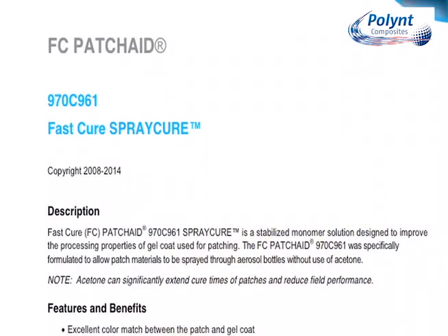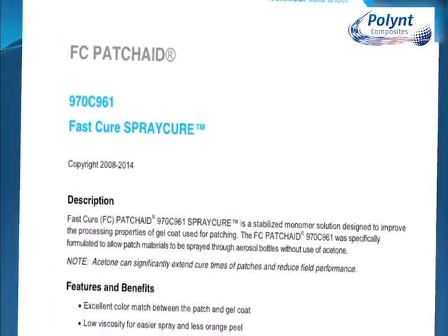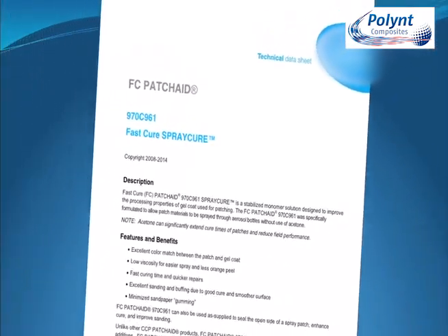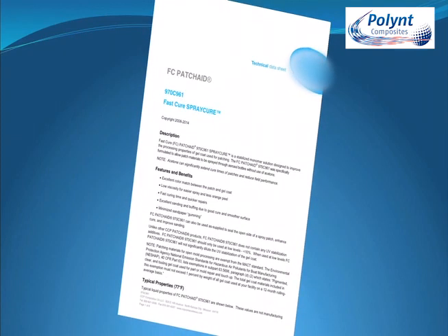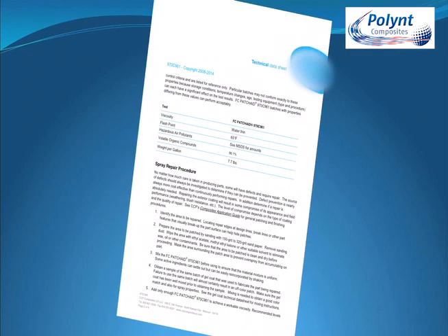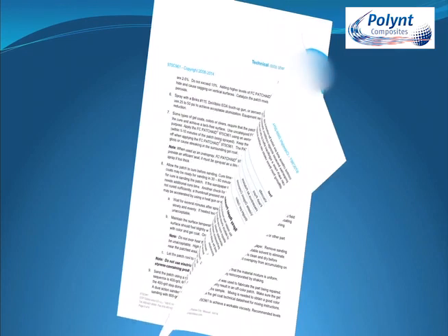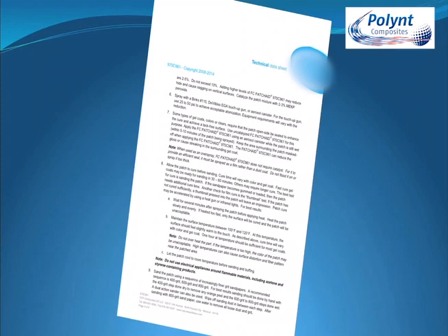If faster surface cure is desired, an overspray of patch aid may be considered for our specialty gel coats. An aerosol type sprayer may be used to spray a film coat of patch aid over the area to seal the patch and enhance the cure. This must be done while the patch is still wet, within 5 to 10 minutes of spraying the patch. Do not flood the patch aid on or spray it too thickly.